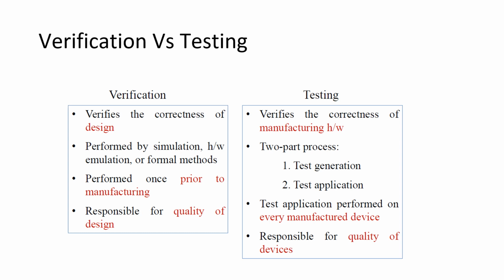Testing has two parts: test generation and test application. You have to generate the test patterns, then apply the test patterns at the DUT and look for a pass or a fail signature. So test has two parts. Please take notes, important topic.